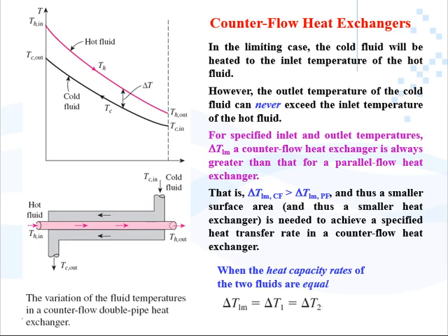The name is self-explanatory. In counterflow, the hot fluid and cold fluid run in opposite directions. In the limiting case, as you see here, the cold fluid will be heated to the inlet temperature of the hot fluid.